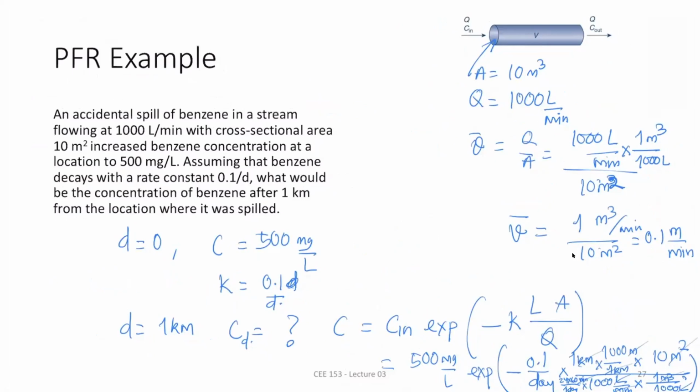Solve all the questions in the examples. So okay, what did we learn? We learned 3 types of reactor. Batch reactor means there is no flow coming in and out. Things are changing because of contaminant reactions. Then the completely mixed reactor, CSTR or CMFR. Here you have flow coming in and out, and you also have some reaction happening. In that system, if you have a steady state, you can solve it. If you don't have a steady state, you can still solve it, using a differential equation. And the PFR, which is a river, a pond, or anything else, is a batch reactor just moving. So that means you use the formula like here, and you just have to plug in those values.